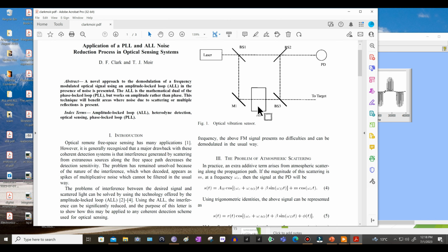It had no limiters in it. I didn't want limiters, hard limiters. It didn't have a demodulator. All it had was, you could stick an aerial up, and it would give you 10.7 megahertz IF out of this device, little module thing. It's quite big actually. And so I used that.